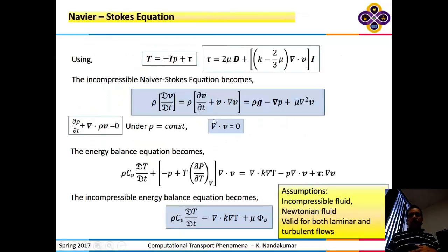Okay, so the continuity equation and the momentum equation, in a very simple way, but in a very general three-dimensional, time-dependent sense. So these two are partial differential equations. There are four unknowns: three velocity components and pressure. If you assume the fluid to be incompressible, the continuity equation becomes del dot V = 0. So it actually doesn't have pressure in it, but pressure is influencing the velocity field that you know from here. Delta P influences V. Okay, and V of course will influence delta P. They are coupled. The four equations are coupled, and